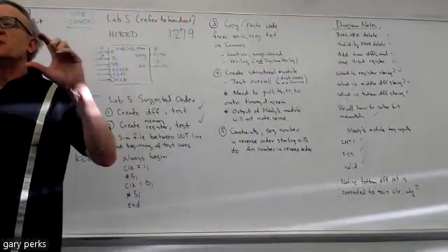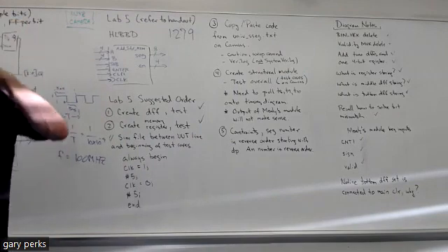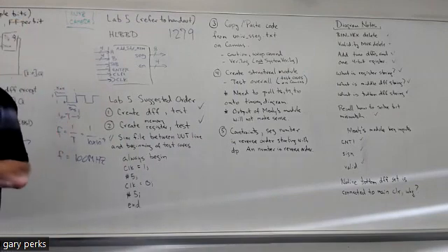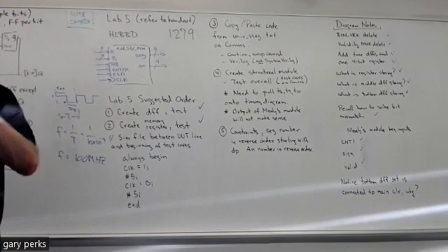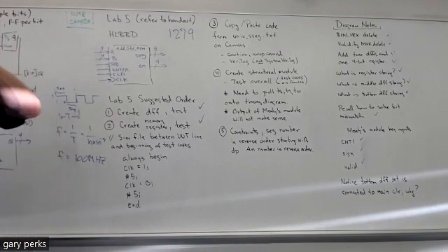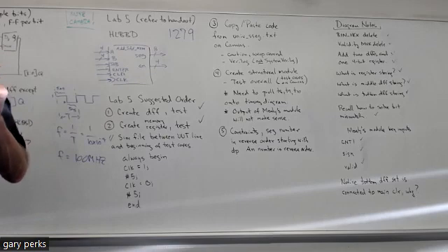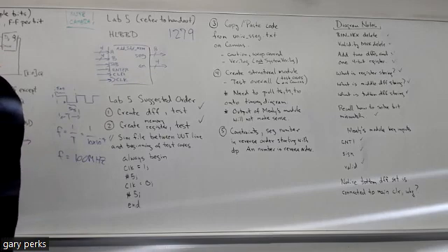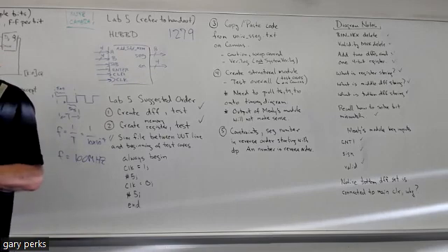Right, because what should display when we hit reset? What should the 7-segment display? Because when you reset, what happens to the output of the flip-flops? Go to 0. So when we reset the entire circuit, we want the 7-segment display to show all zeros. Well, it's only going to do that if your validity is 1 while your reset is active, right?